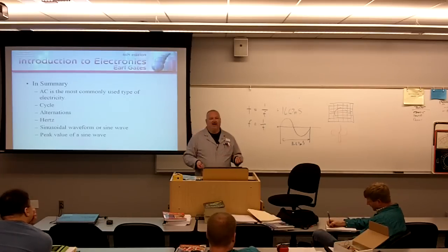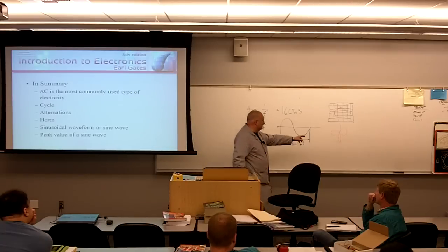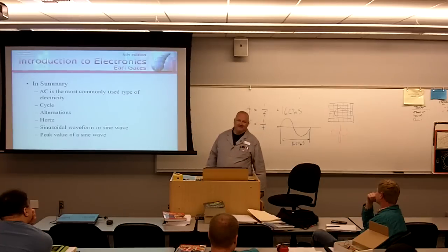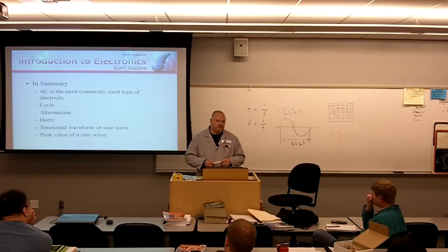By having that connected like that, I'd look at the computer and then immediately patch it up to the oscilloscope. Look, circle. Yeah, the computer's not lying to me. Or, no, I'm getting one of these. The computer's lying to me. This isn't even the frequency that we're at. It's lying to me, so I could discount that and move on. It's called a Lissajous pattern on the oscilloscope, and I'll show you in the lab someday how to do that. It's kind of cool.